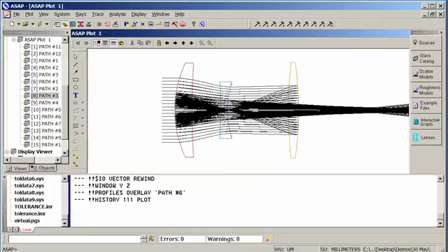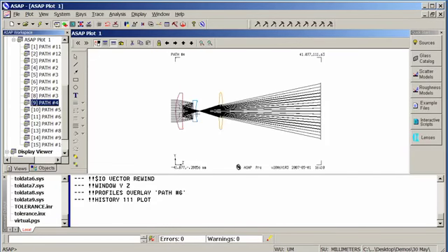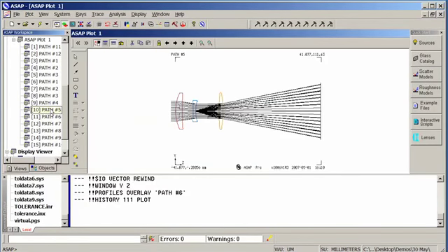Notice, again, we have a concentration of energy very close to this particular lens, just like we saw on one of the first order bounces previously. The next path, this lens is definitely seeing a lot of effects of Fresnel reflections. With a high power source in our system, this could cause a problem. Same with this path. Not much of a problem on the detector, but we do have an energy concentration that we might need to concern ourselves with.